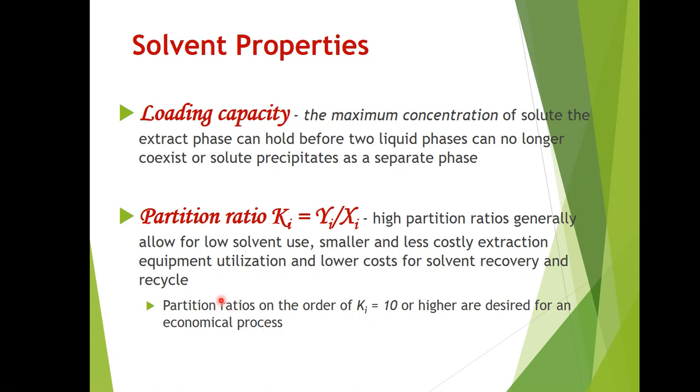That recovery will entail lesser cost if the partition ratio is high. So most solvents, after being used, are recovered. They are not discarded. They are recovered by another unit operation of separating the component from this particular solvent, and that process is solvent recovery and recycle.